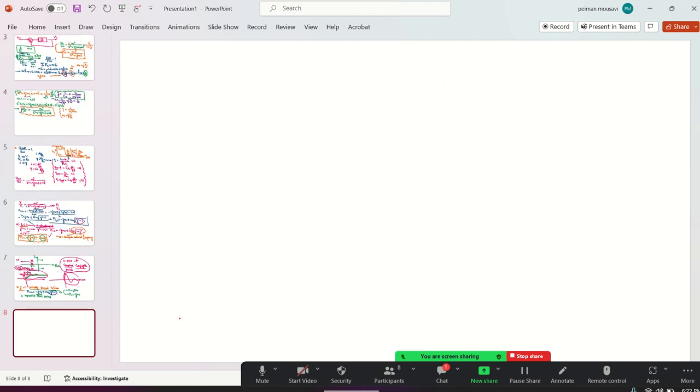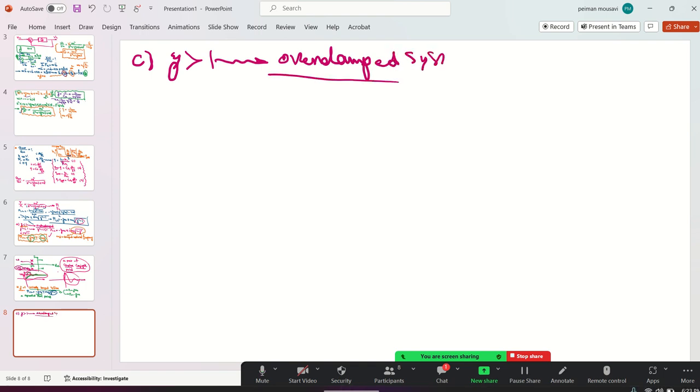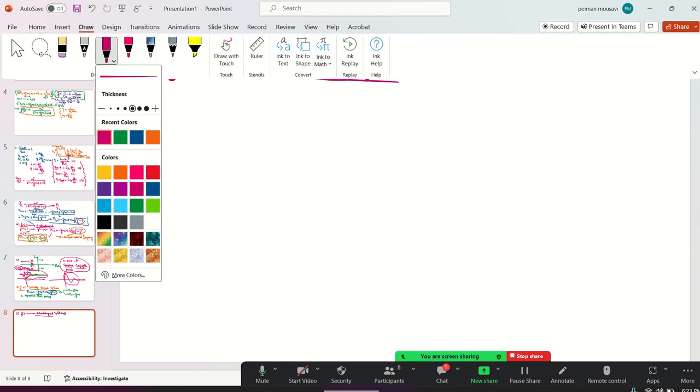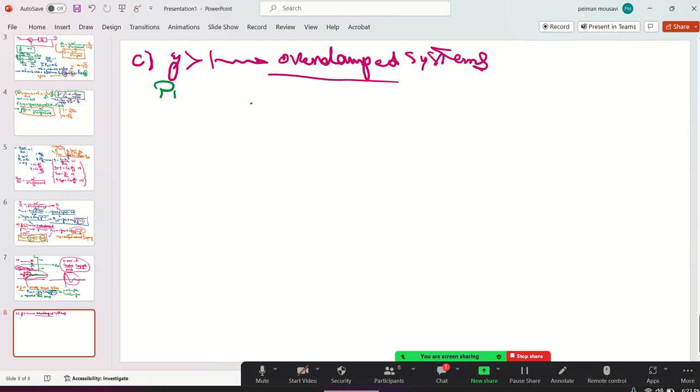Okay. C. In the literature of vibration, robotics and control, if you add a little more damping, zeta is greater than 1. We're going to name it an overdamped system. It's extra damped. So for an overdamped system, looking back to high school, we had two poles of the system, the original one: minus zeta omega n plus or minus omega n square root of zeta square minus 1.